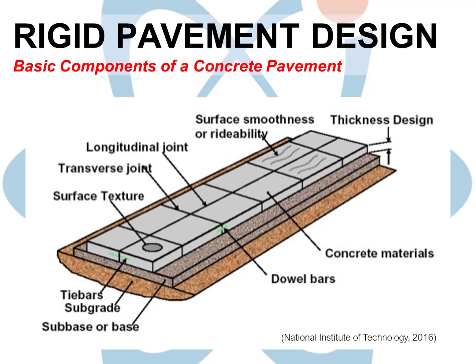Concrete pavement contains joints to prevent or control cracking, shrinking, and curling. Essentially, they allow the concrete to move, thus preventing or at least lessening damage. But if not properly designed, joints can actually cause problems instead of fixing them. You've all experienced the bump, bump, bump of riding along a freeway in a car or a truck. These bumps are the result of inadequate pavement design and in particular, inadequate joint design.